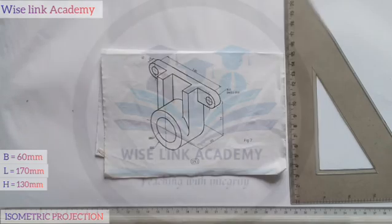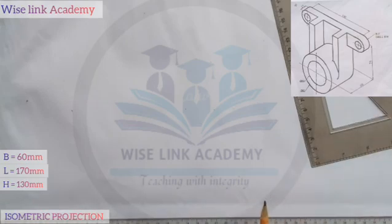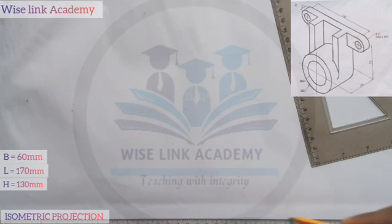Right? So now let's start producing out the figure. First thing first, our first task here is to draw our isometric axis, right? So doing that, if I want to draw my isometric axis, what will I get? Drawing my isometric axis, I will take my t-square down this way, and I will draw a horizontal line, right, as you can see in front of you.